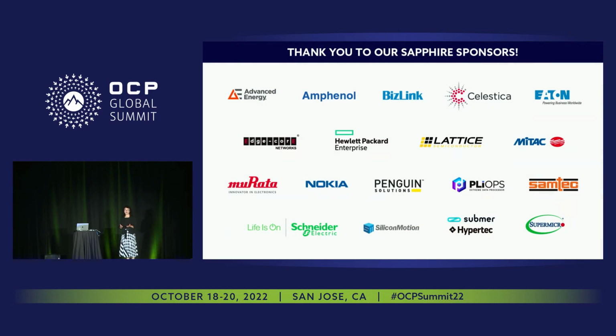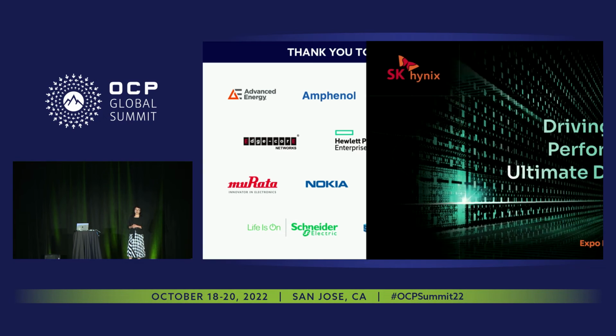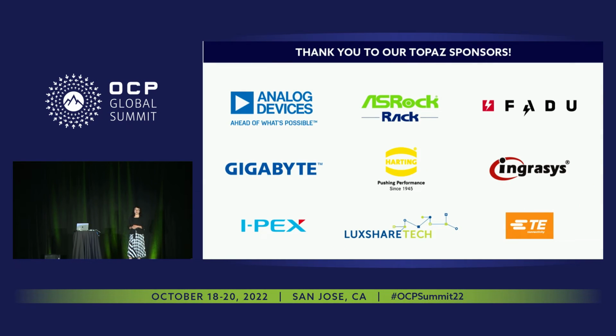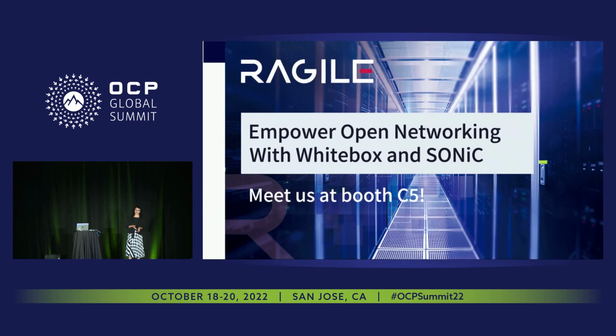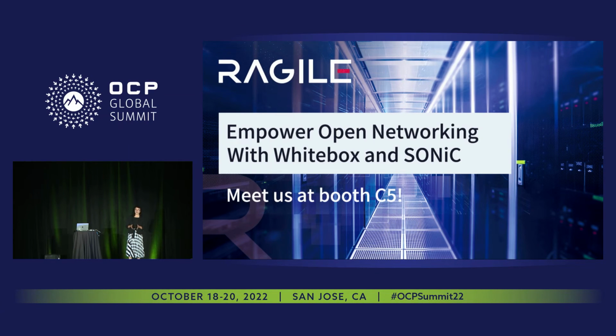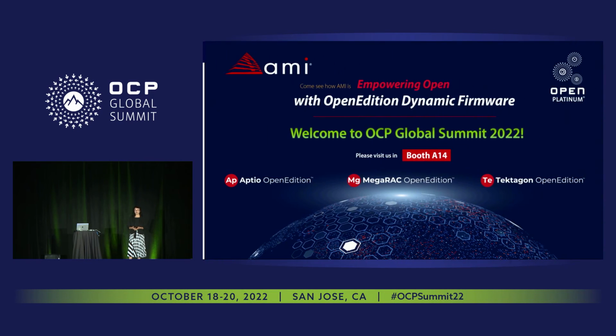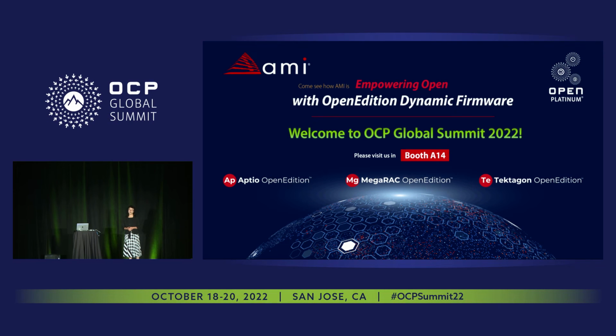The second reason is pitch reduction. If you want to do pitch reduction using micro bumps, currently the smallest micro bump pitch, as everyone knows, is 55 to 40, for example, and 35 is being studied under development right now. But with chip first, you don't need micro bumps. That's why your die-to-die bump pitch can be reduced to 20 or 25 microns. So this is the key. Which one you choose depends on your performance requirement and on how much tolerance your design can give.